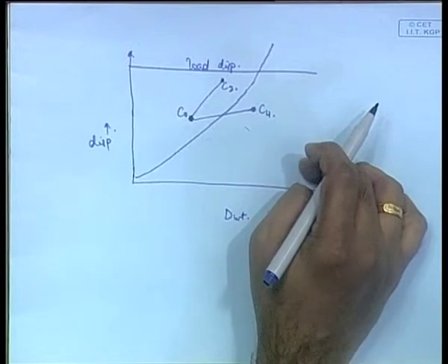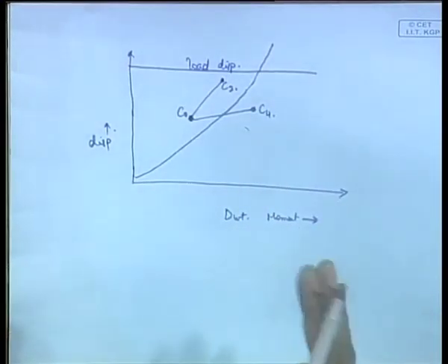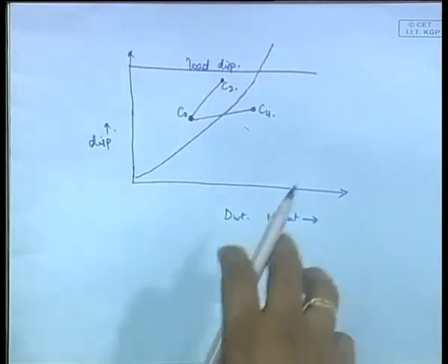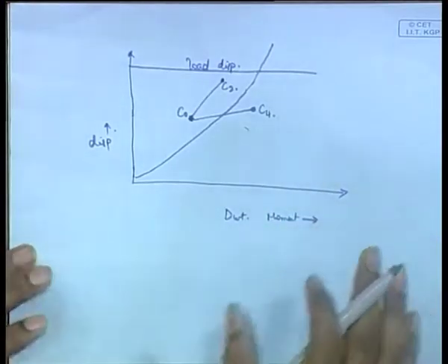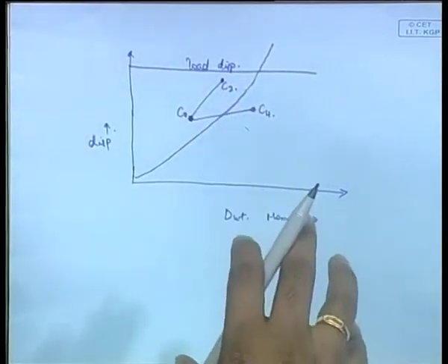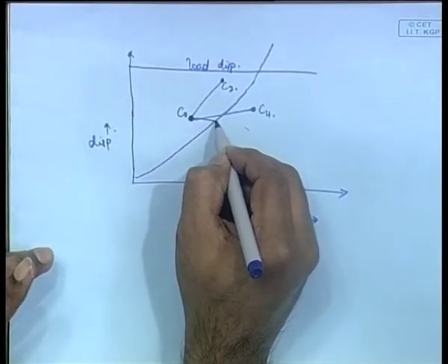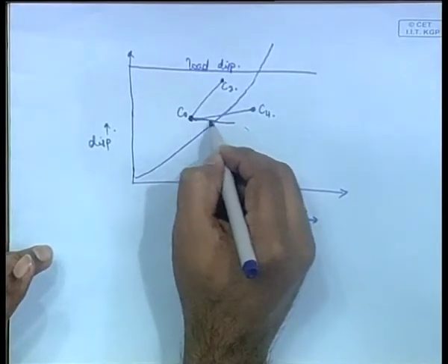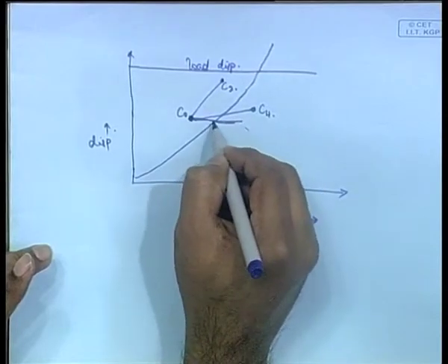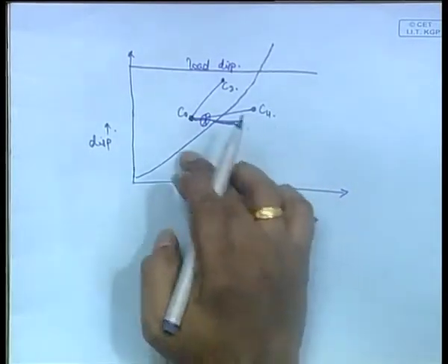Another possibility is that you can change the dead weight moment without changing the displacement of the ship itself. You are moving one weight from one point to another point, and as a result the moment has changed. So, it will go horizontally; the displacement will not change, and after a particular value it will cross the curve and become unstable, till then it is okay. So, these are different stages.